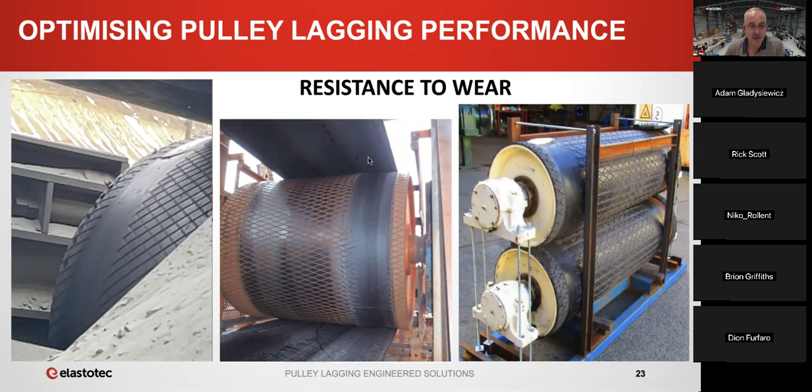Now, if you just look up at the top of the belt here, I don't know if you can see this, but leaving this wear problem, not doing anything about it, you can see what it's been doing to the belt. It's actually worn through the bottom cover and exposed the cords. So the problem shows up in the lagging first because you've got much smaller surface area. But if you don't do something about it, it'll eventually turn up in the belts as well.